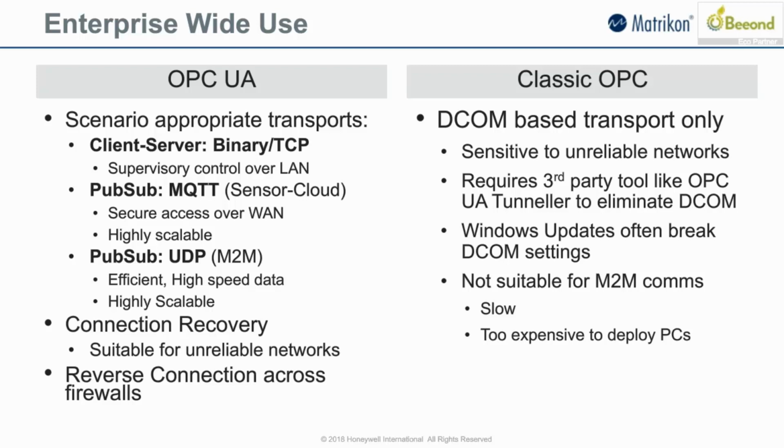But now we've got new interesting scenarios where, when you want to talk to cloud, there are technologies that we have now that are very good at doing just that. And MQTT is a very popular one at the moment. So that transport is now also part of the pub/sub spec, which just means that you're still keeping all the other functionality that OPC UA has, whether it's the context or how security is established end-to-end, but it now can run over MQTT and run as pub/sub, which just means that the server, let's say, would take the role of typically a publisher, starts publishing data, and servers or subscribers sitting in the cloud could just pick that up if they have the right permissions over MQTT.